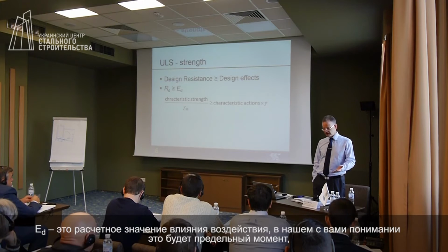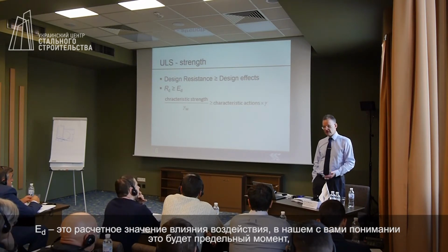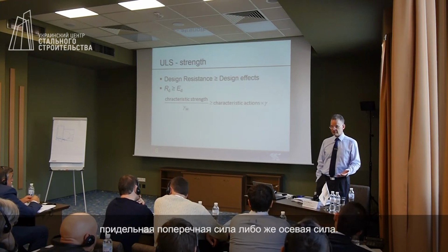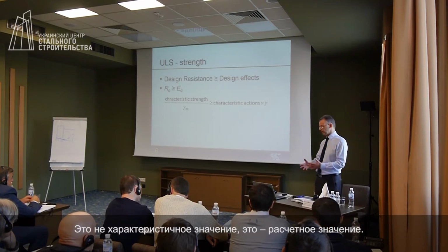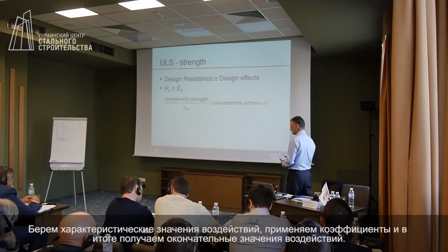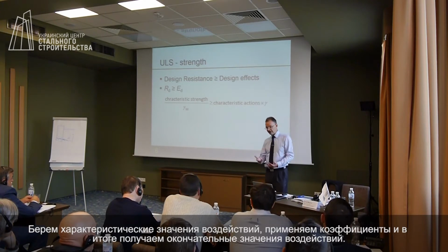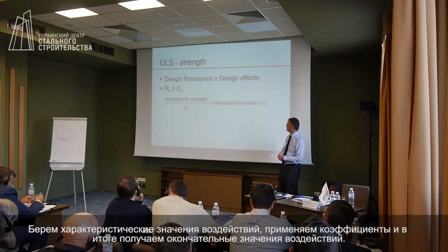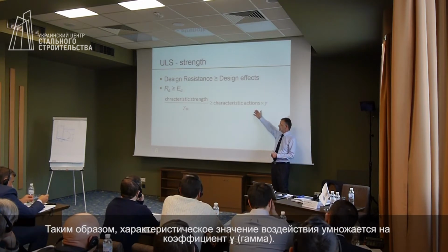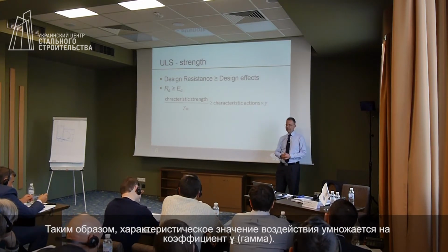And as far as you and I are concerned, ladies and gentlemen, that will be the ultimate shear, or the ultimate moment, or the ultimate axial force. It's not the characteristic effect, it's the design effect. We've taken the characteristic actions, we've factored them, we've increased them, they are the ultimate actions. So the characteristic actions multiplied by a gamma factor.